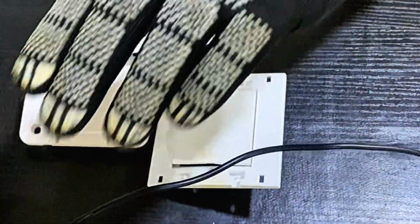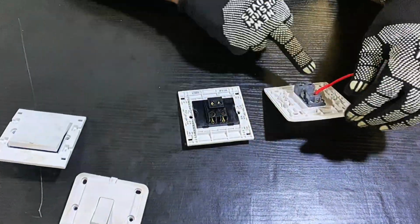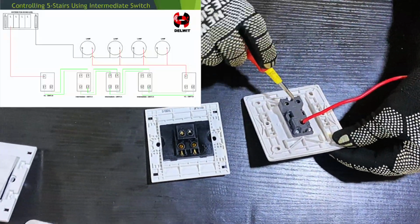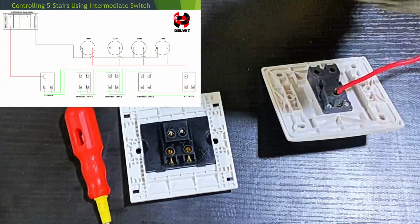The next thing to do now is the traveler. So we're going to have a traveler coming from here to here. On the circuit, we said L1 is connected to the L1 of this, L2 is connected to the L1 of this. So we're going to take 2 traveler wires to do that connection.